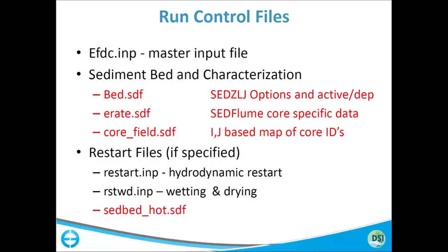So you've got a hot start file, you've got all your output from the prior run. You turn on your run continuation, hit run. Well, you have to save, turn it on, hit save, hit run, and the model will just crank right up from the last restart file. And all your output will be in one nice continuous file. So it's a usability issue. It's quite helpful.